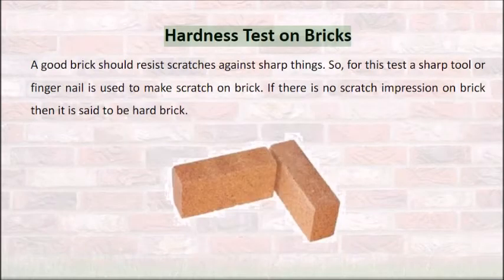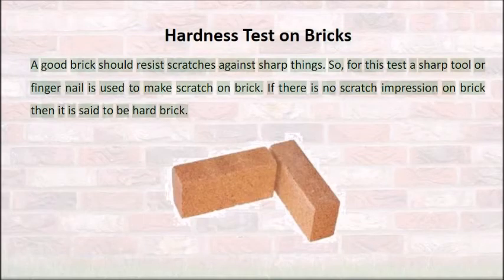Hardness test on bricks. A good brick should resist scratches against sharp things. So, for this test, a sharp tool or fingernail is used to make a scratch on the brick. If there is no scratch impression on the brick, then it is said to be a hard brick.